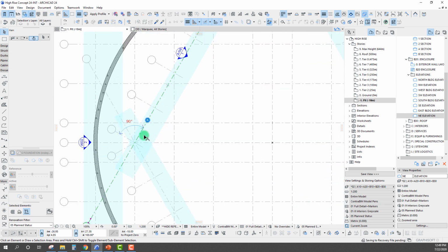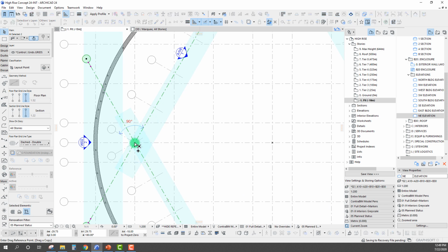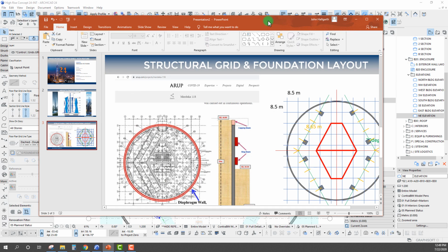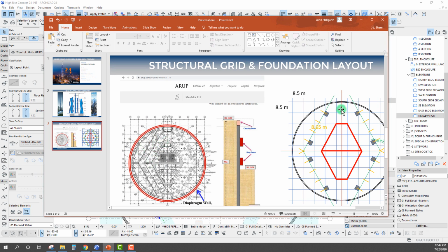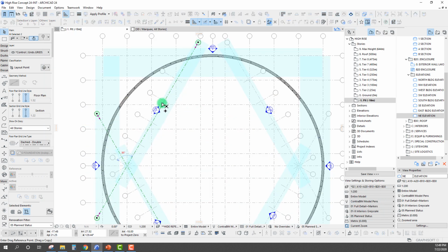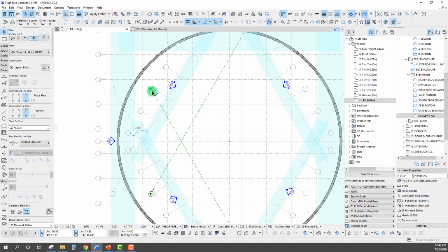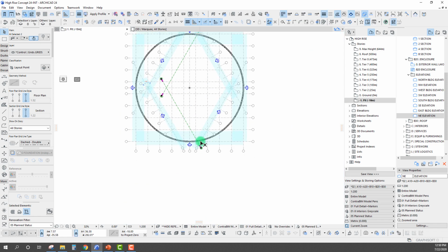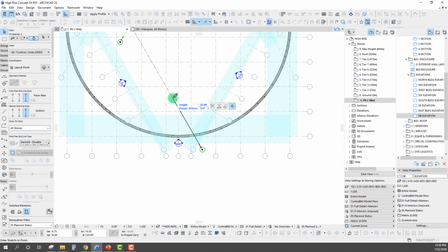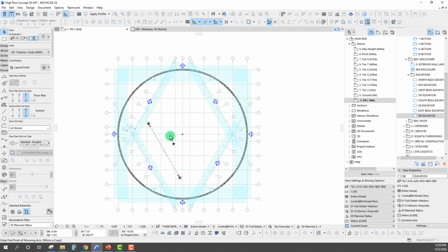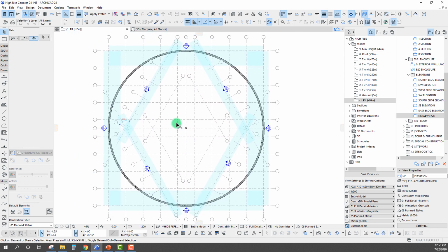And then finally here, I think what I'd like to do is create some grids for where we think our core is going to end up. And in this case, I'm actually going to pull this back over here just for a quick reference. I think our core is going to end up right about at that intersection, so we can just set it at that. So we're going to take this one, push it on over, and snap it right there. And then we can do some quick offsets here as well. So we'll just snap that one. Snap that one. May not be exactly perfect there, but probably pretty close. Snap it to there. Let's make it perfect. It's easy enough. So take this, mirror, mirror, and okay, there we go. We have all of our grids set up.